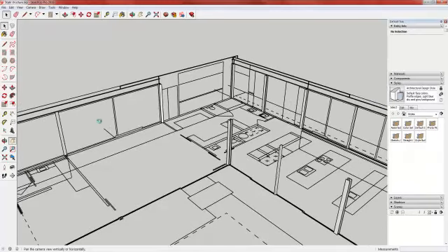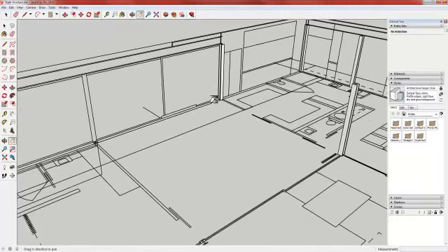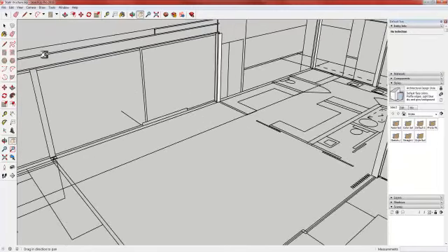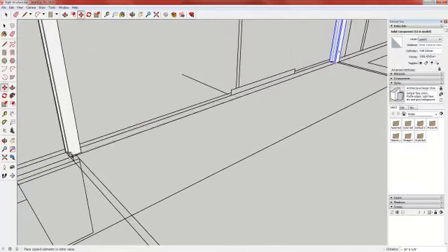So we do have columns that run across the other side of the building. So what we'll do is go ahead and take care of all of our columns while we're doing it. Let's double check that that one's facing the right way, and it is. And we're going to go ahead and make a copy of that column. And we'll again hold down control while using the move key. And I'll place that. And I'm going to just type in X5 and see what happens.